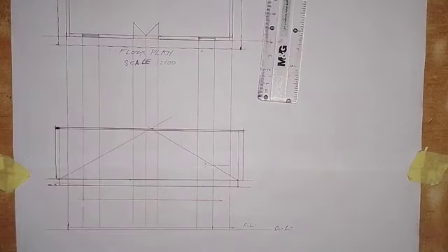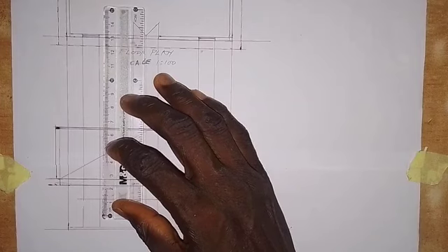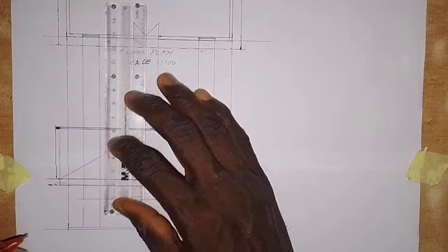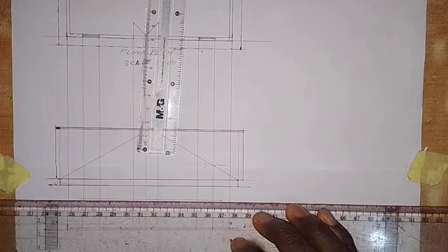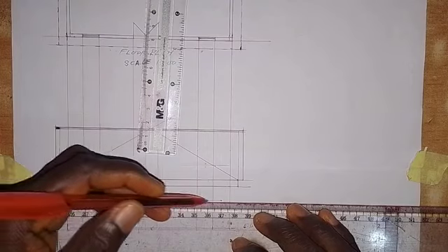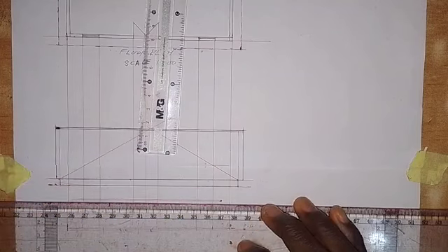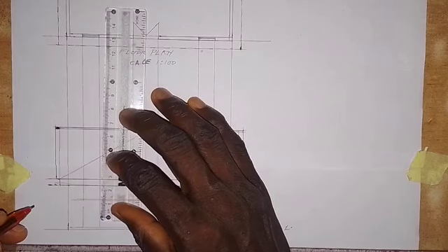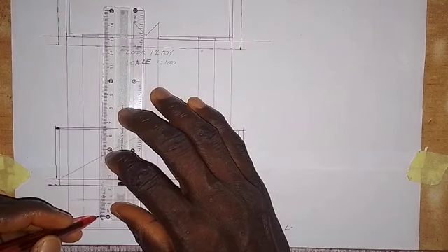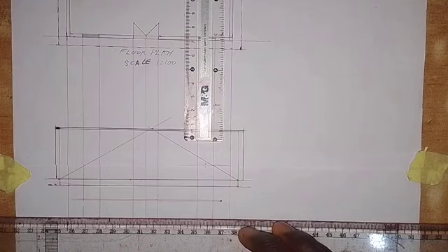All right, so now let's go and construct the window. What we have to do now is take a measurement of 12 millimeters, and before that we also need to take a measurement of 1 millimeter for the frame of the window. So just take 1 millimeter down. I'm not going to be taking that measurement, I'll just draw. The same thing applies to that of the door. So just draw this horizontal line as I've done it here. From the second line that we just drew, take 12 millimeters down. So this is 12 millimeters here. Here you draw a horizontal line again.